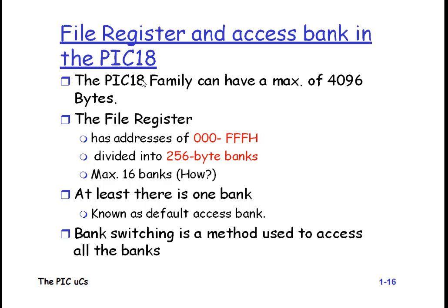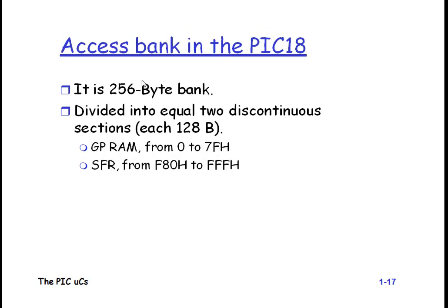So how is it possible? At least there is one bank which is known as the default SFR bank. So bank switching is a method used to access all the banks. In PIC 18, as you see in previous slides, it has 256-byte banks, divided into two discontinuous sections, each with 128 bytes.